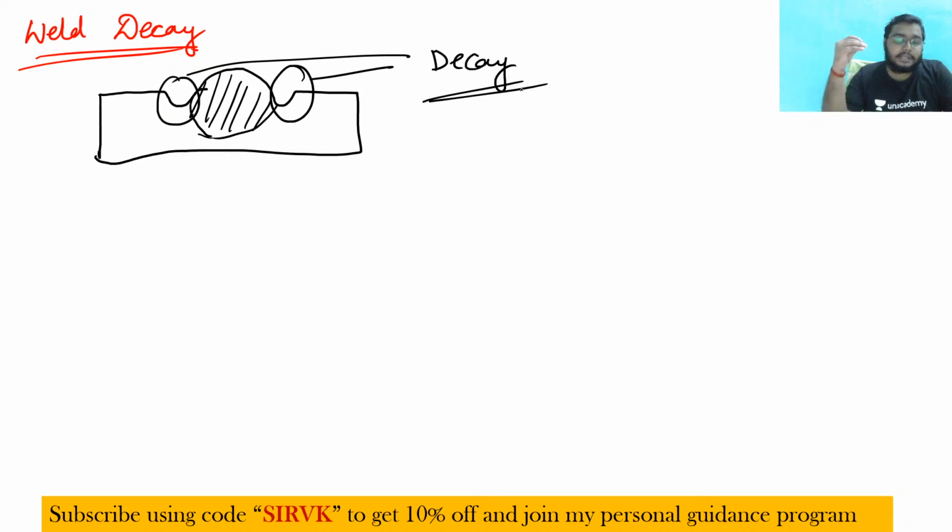In the case of stainless steel, due to the fast rate of cooling, whatever chromium is present in it, see, when you are doing the welding, this would be the heat affected zone. In the heat affected zone, the chromium is converted into chromium carbide.